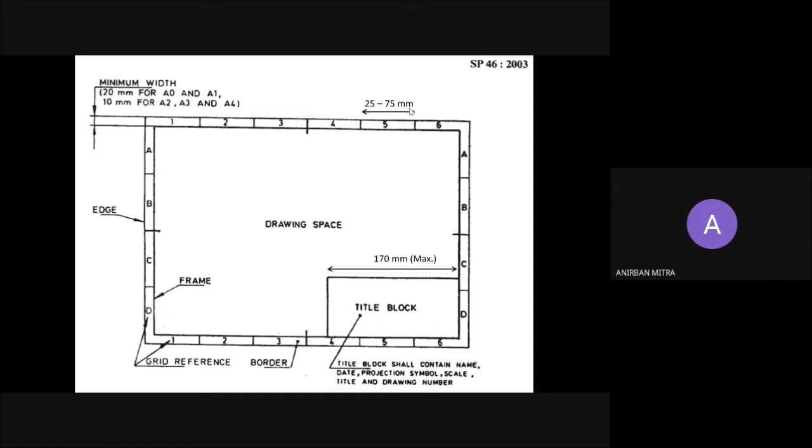You know what kind of sheet you are using. If you are going for A4 sheet, then its dimension along the length would be 297 millimeters. You have 10 millimeters for the margin from both sides. So you can take out 20 millimeters.